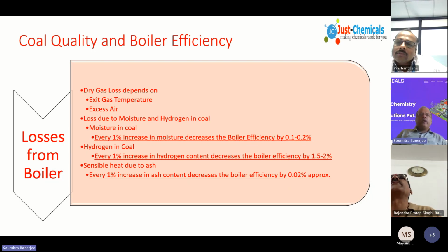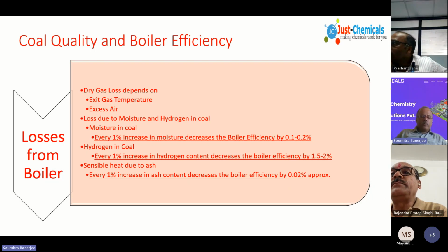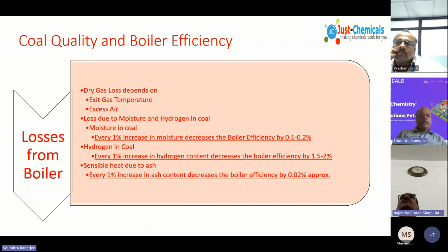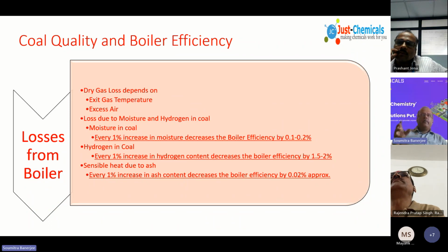So that is good. See, boiler efficiency, sir: what we do is we calculate the boiler efficiency by the enthalpy generated in the superheated steam divided by the kilocalories of fuel burnt, into kg of fuel. Now, boiler efficiency means that our efficiency may have come down as compared to the kilocalories being given.